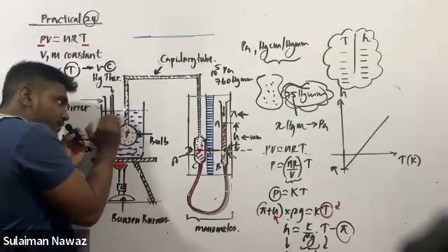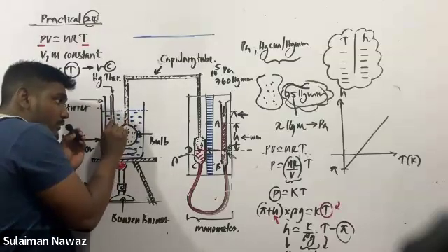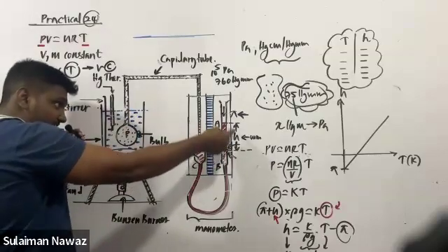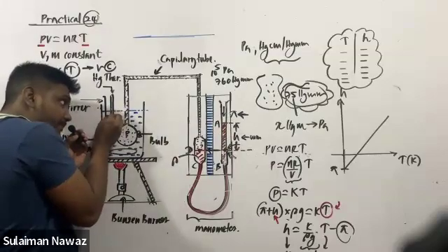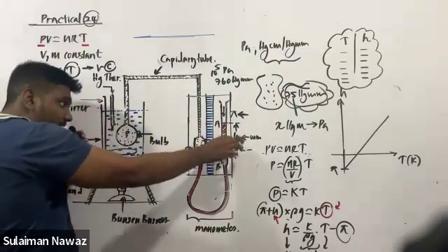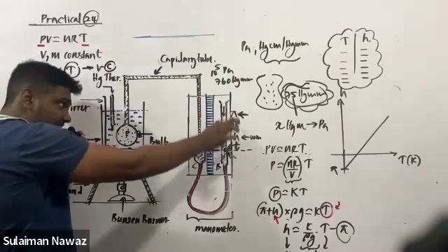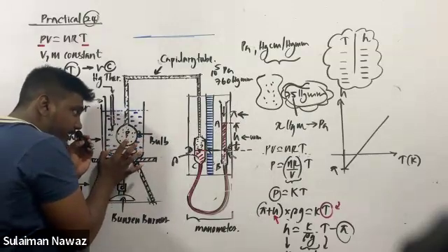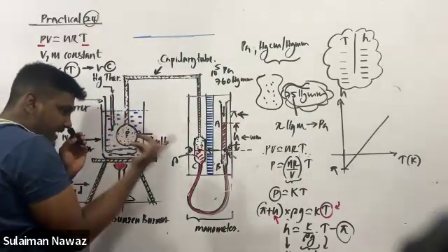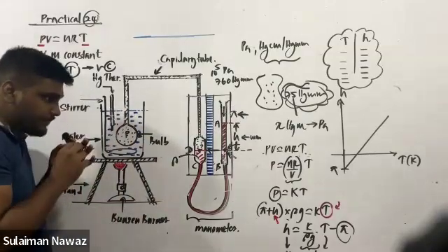The thermometer reading should be constant. And also on the other side, you want to check this height also. If you notice this height is fluctuating, this height is varying, then understand the temperature of the bulb has not reached the thermometer reading. That is the idea.